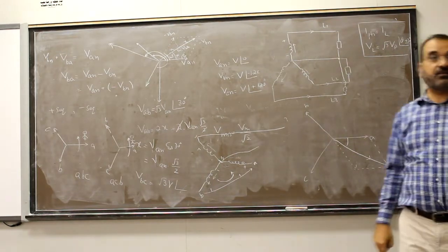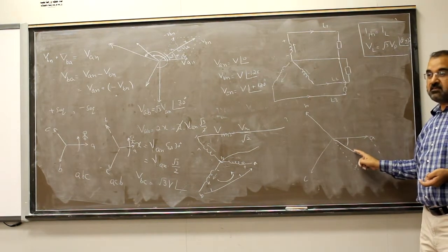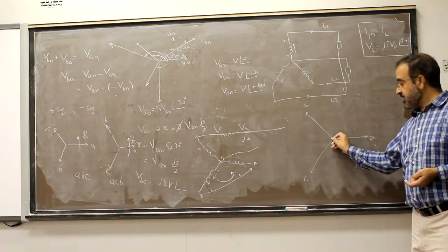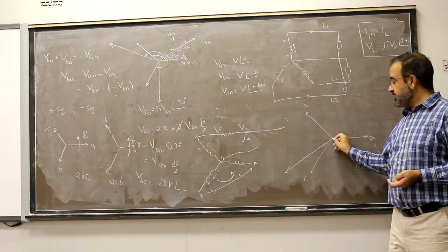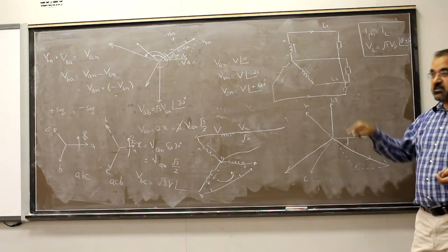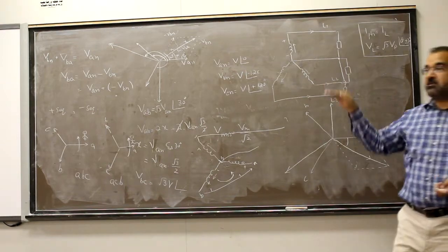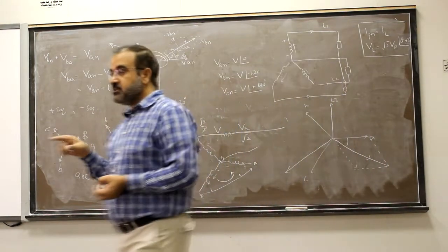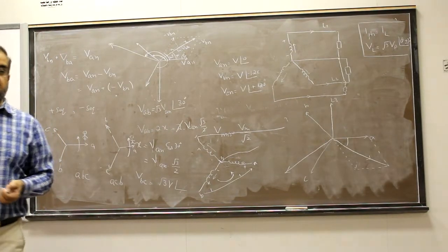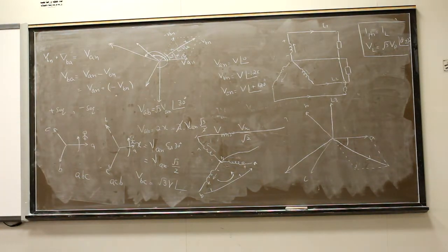So this will also be minus 120, and here it will be this minus 30 degrees. Here again it will be the second one, and here it will be 90 degrees. Understand? So in both cases you will add plus 30 degrees to the original phase voltages in case of positive sequence, and minus 30 degrees to the original phase voltages in case of negative sequence. The currents are the same for phase and line in both cases. Currents are the same in both line and phase value.